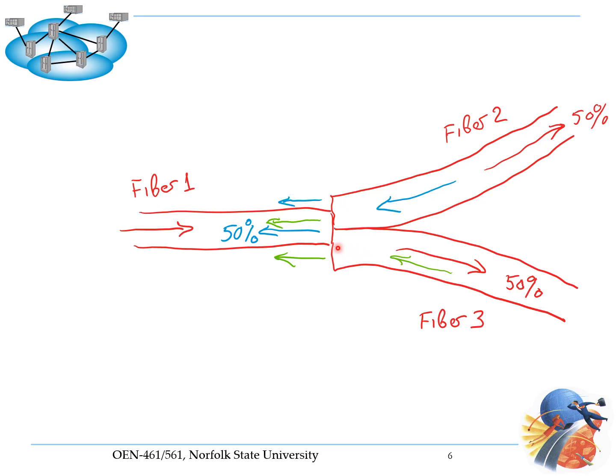Once light comes to the interface between fiber 3 and fiber 1, 50% just goes outside the fiber and is lost, and only 50% will continue through. It's just a schematic, it's not a realistic schematic, but it gives some sort of physical understanding of what's going on inside a Y branch, even one built not using fiber technology, but planar waveguide technology. Still, no matter from which side we start the light, we will still suffer 3 dB losses.